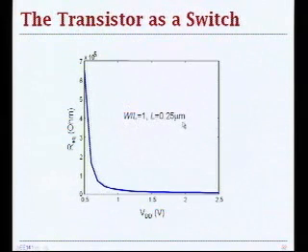But it's important, if you assume that the channel length is 1/4 micron, we simply scale the resistance by this W over L ratio. So the wider the channel, the less resistance you have. And you can basically just use these numbers and scale with appropriate W relative to your minimum W given here. And as you see, when you keep decreasing your voltage, you have a sharp increase in your equivalent resistance. Where is that coming from? Any guess?